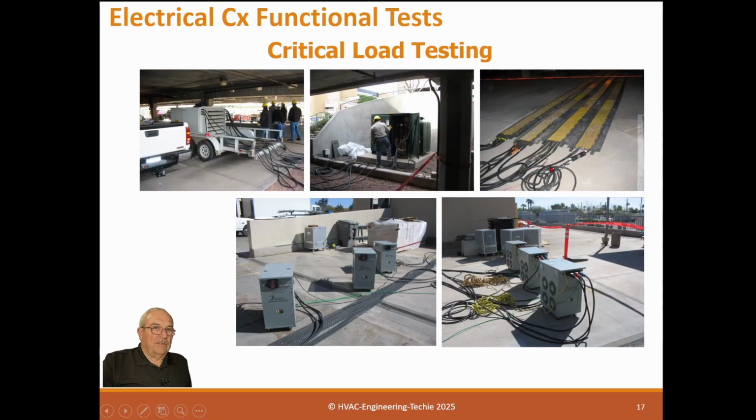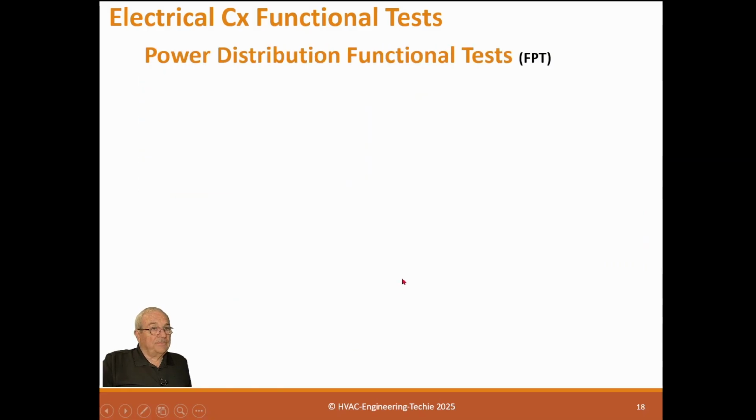So the load banks have to be wired up with cables, and you have to put guards on them so someone doesn't trip over them or so that you can drive over them. And so it's pretty intrusive, and it is expensive to set these up. And you want to do all the tests you need on load while you've got the load banks present.